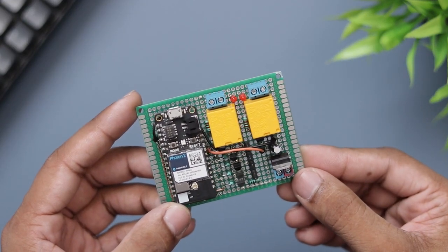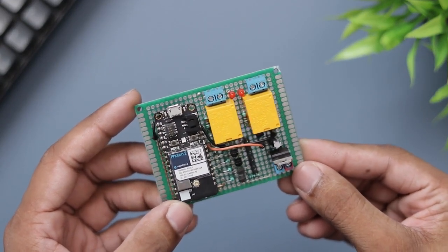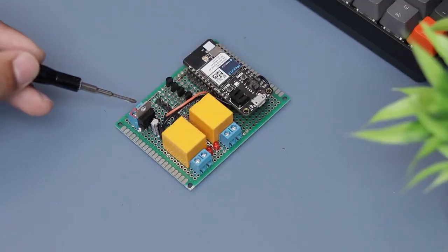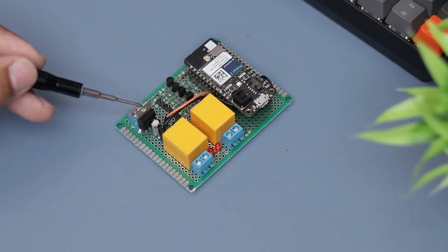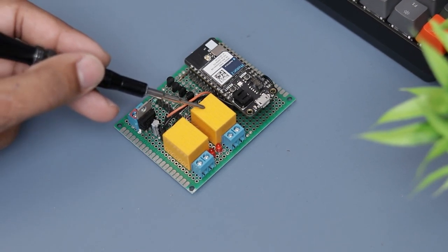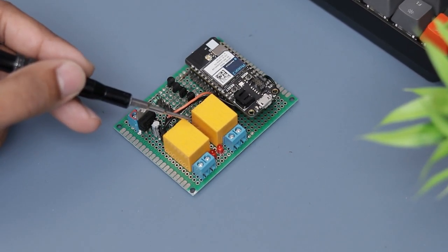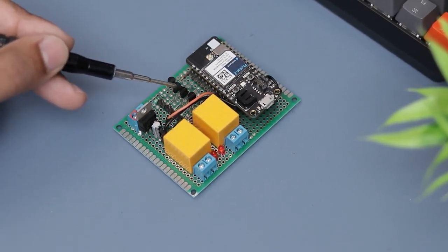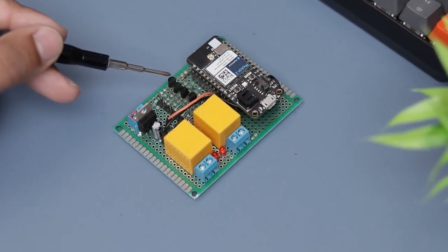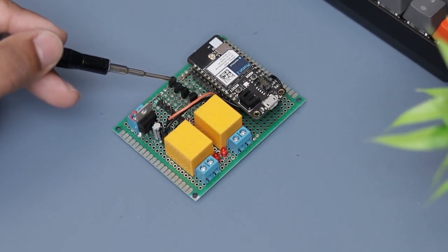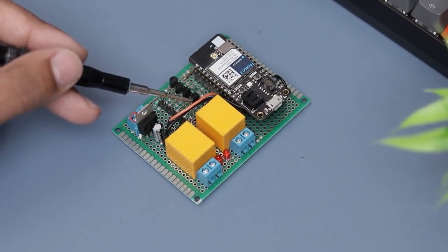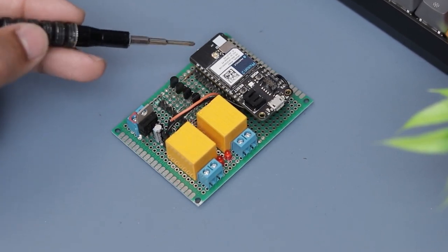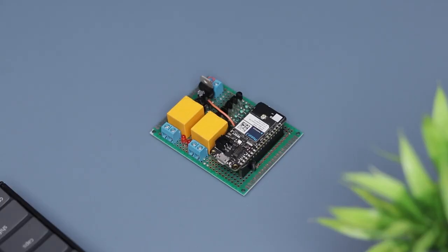Okay guys, so our project is nearly complete, but before we delve into the coding, let me clarify the circuit board. It runs on 12V DC. Here I am using a voltage regulator IC to convert the 12V to 5V. Next we have two relays, one for automatic on-off and the other for manual operation. Then we have 4 transistors for each level percentage. The first one for 25%, then 50%, 75% and 100%. Finally, we have the main board, which is Photon 2.